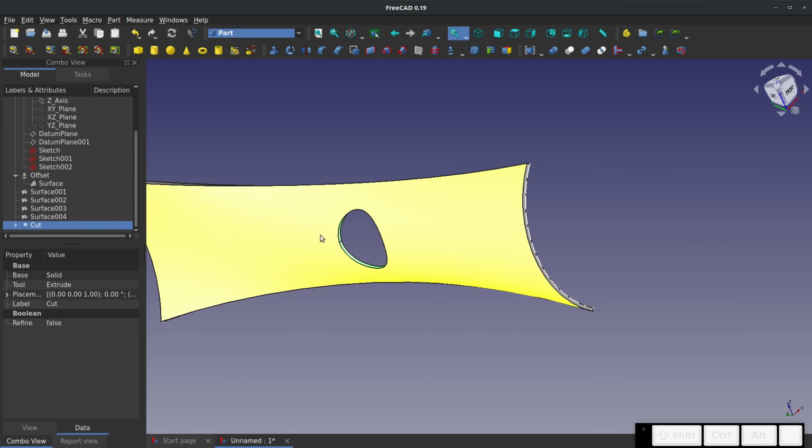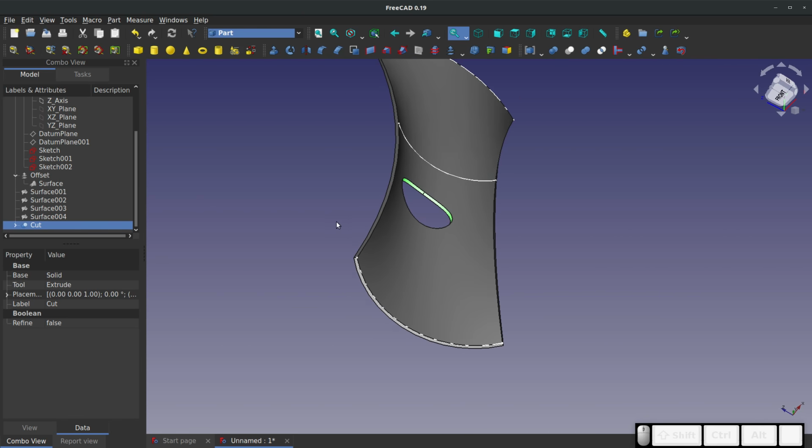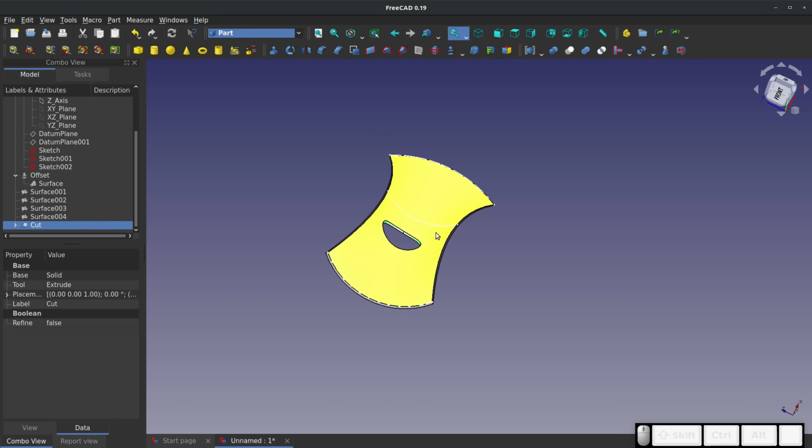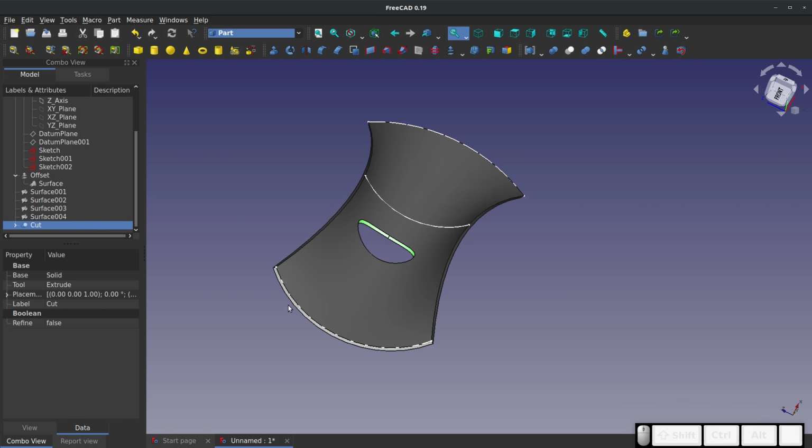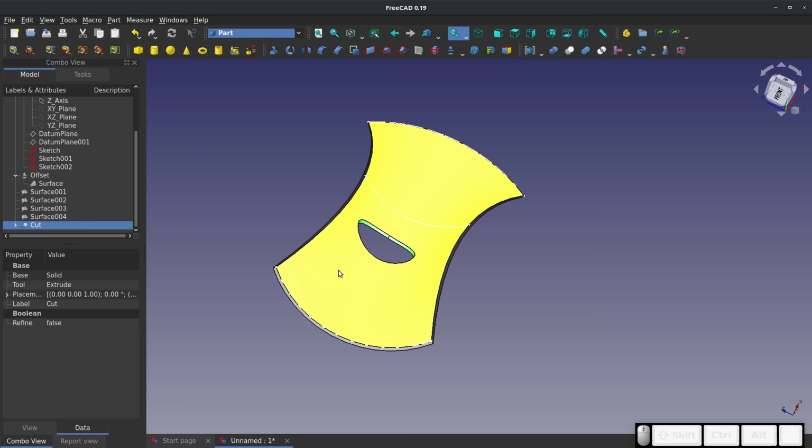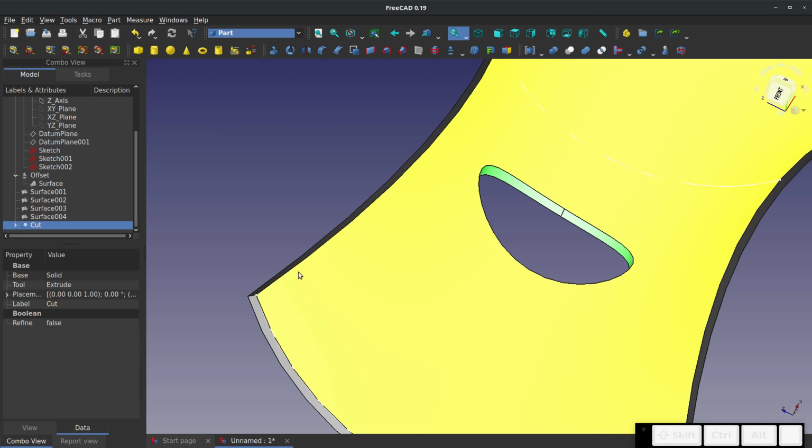So we know that that's solid. So a few strategies, right? With surfaces. You can make your surface and offset it and fill it. You can make a surface to edit a solid with, or you can make a surface and make it watertight like we have here, and then convert it into a solid. And those are ways that we can use surfaces to augment our abilities in modeling that it would be difficult to do otherwise.